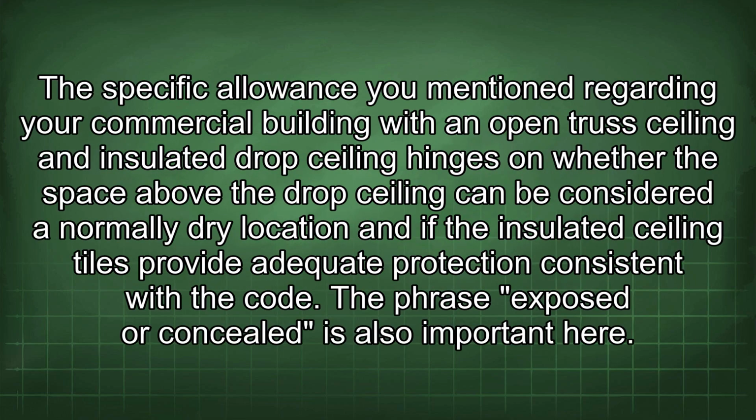The specific allowance you mentioned regarding your commercial building with an open truss ceiling and insulated drop ceiling hinges on whether the space above the drop ceiling can be considered a normally dry location and if the insulated ceiling tiles provide adequate protection consistent with the code.